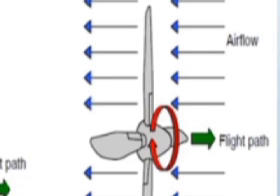It simply means that when the propeller rotates as a result of the engine turning, it blows air from the front and sends it to the rear. By so doing, if the air is enough and the acceleration or velocity is also enough, you achieve much thrust, in the rearward direction, which will cause the whole aircraft, because the propeller is attached to the engine and is on the aircraft, to be moved forward by Newton's third law of motion. So basically, that is how thrust is produced by the propeller blades.